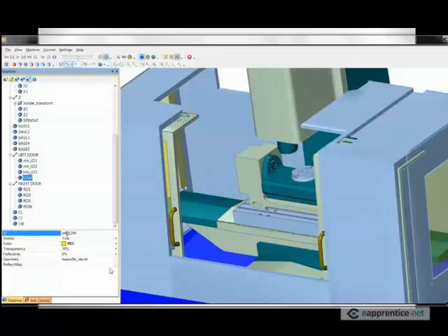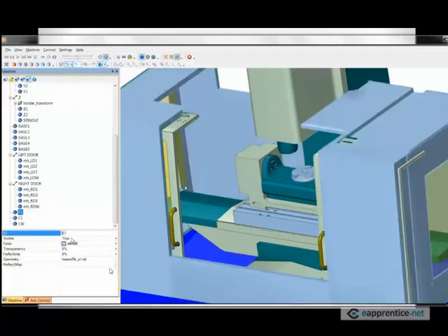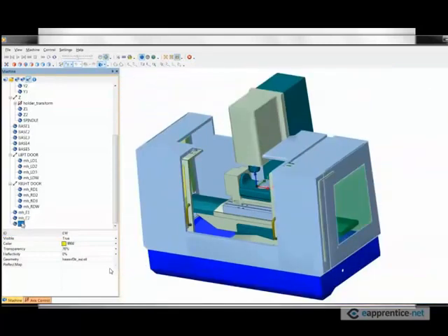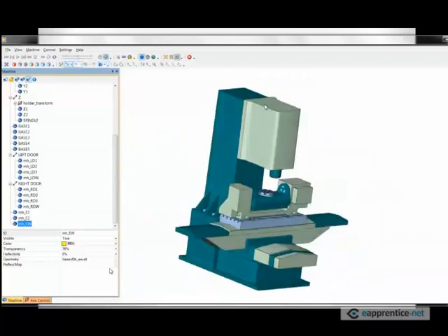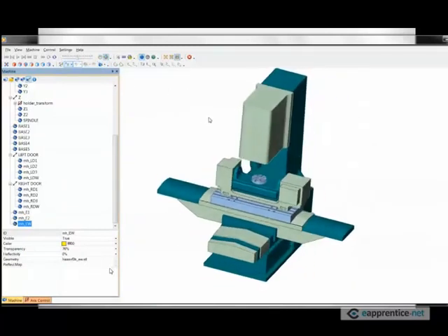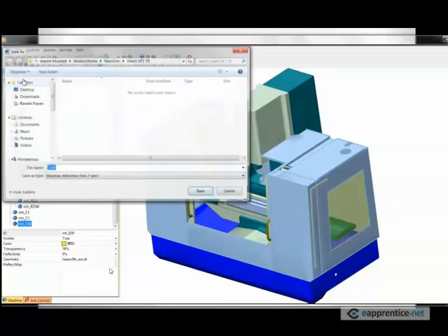Let me just do a few more here and show you. Let's do the enclosure MH underscore here, and number 2, and those windows too, I want to make them disappear. So once all this is set, I have this button up here. If you click on that once, things go translucent. Click twice, they disappear. Click again, they come back. This is a quick way of getting rid of the enclosures.